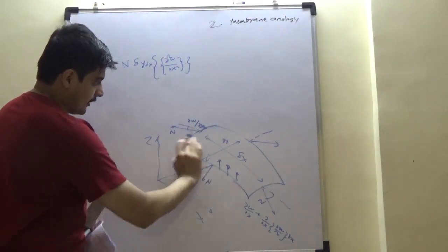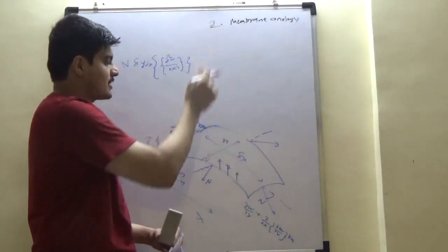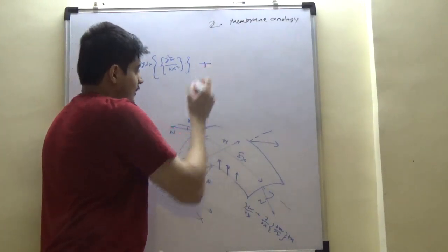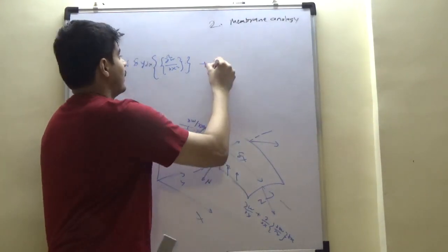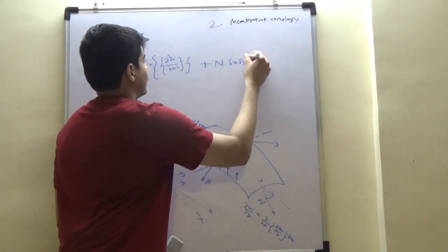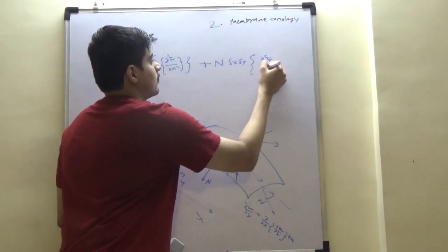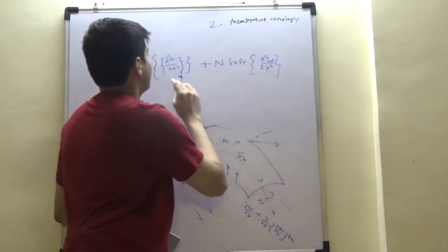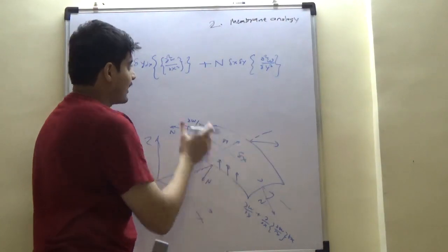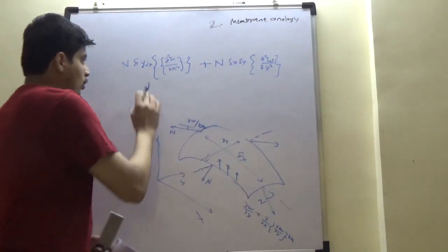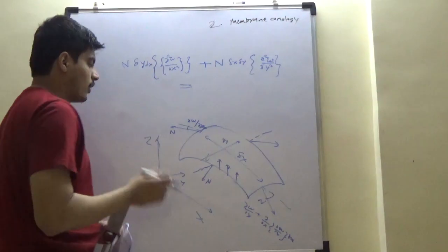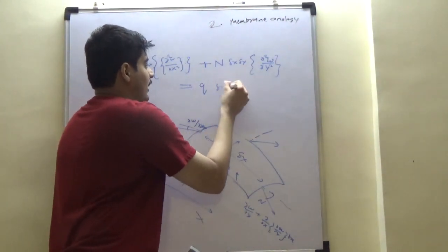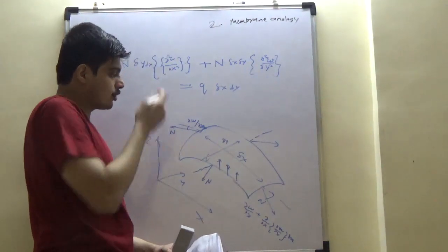So the double gradient of this displacement in Z function is going to play a role. The second component, by the same reasoning, can be said to be del square W by del Y square, and delta X delta Y is again the normal. Both of these have to together resist the load Q delta X delta Y, because these are the summation of the force.